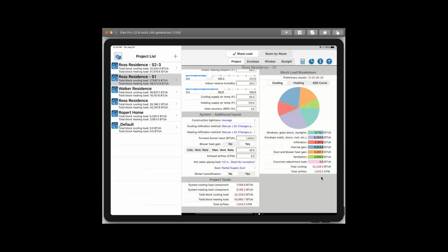Okay. I was actually talking about like a Zehnder ERV system where there's no furnace, it's just the HVAC. Oh, so are you talking more commercial type? No, residential. You use an ERV system. That exhausts about the same amount it supplies, and the ERV reheats to about 85% efficiency, 90% efficiency.